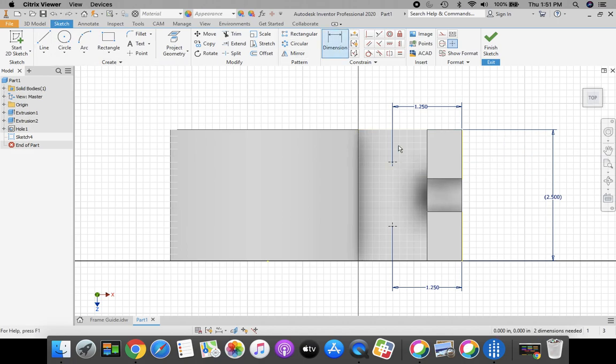So I'm doing dimension tool. I'm dimensioning from the top of my block to the top point. Bring this out. And what do I want in here? I want the overall dimension with this dimension that's in parentheses. And I'm going to divide by 3. Divide is backslash and then 3 because there's going to be 3 equal parts when we're done. Green check mark. Hey, great job.